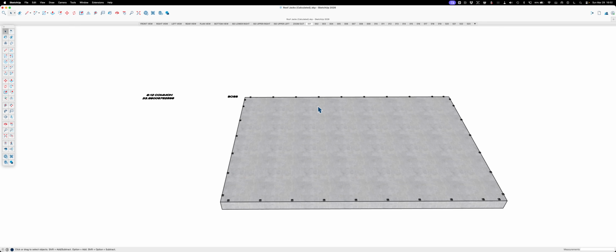From what I understand, and I'm not really a good person with Layout from SketchUp, you set up scenes like you see right here where my cursor's going. And when you're in Layout, you refer to these scenes. So you would set these all up with your section views and your plan views and stuff.